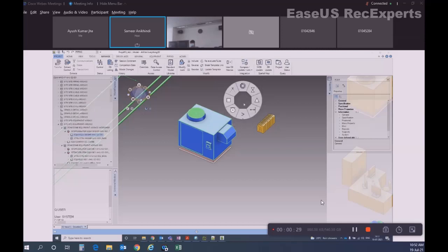If you go to more, you will see intersection, corners, endpoint snap, tangent snap, midpoint, nearest. This is laser snap, laser data snap. You can load laser data in E3D and snap those point cloud data. Then this is a distance snap, and then you can go here: center of the circle, parallel, perpendicular from, perpendicular to, quadrant, and extension.